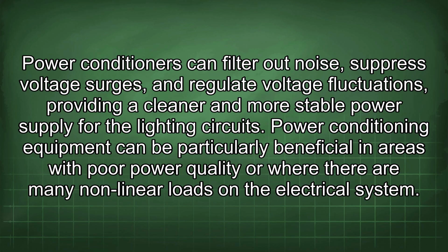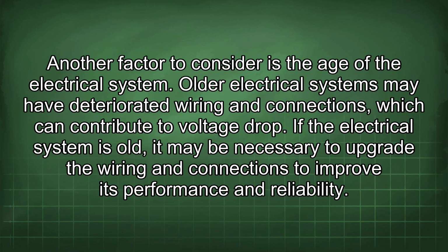Another factor to consider is the age of the electrical system. Older electrical systems may have deteriorated wiring and connections, which can contribute to voltage drop. If the electrical system is old, it may be necessary to upgrade the wiring and connections to improve its performance and reliability.